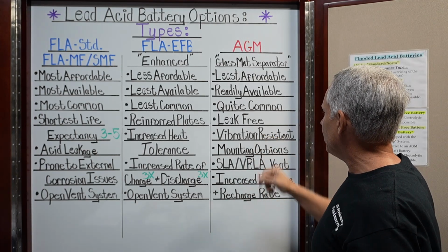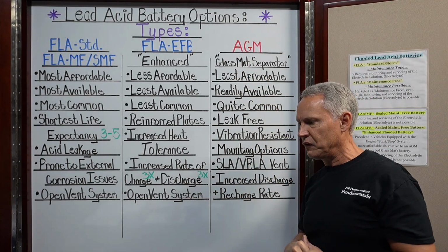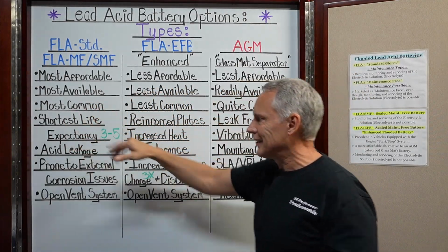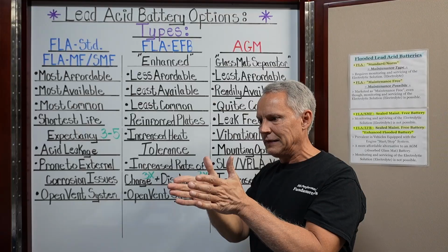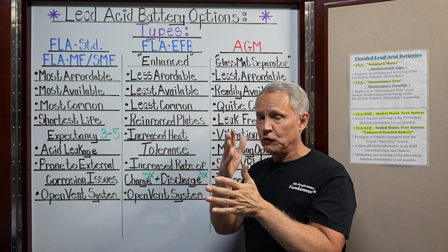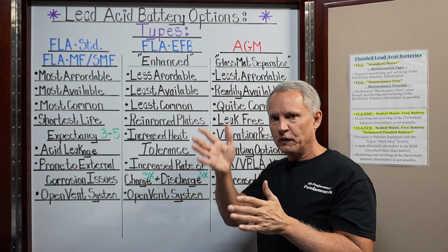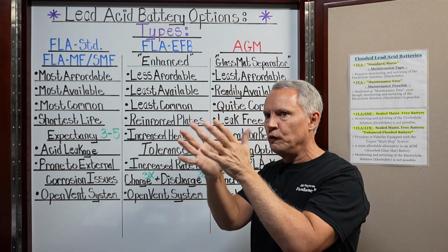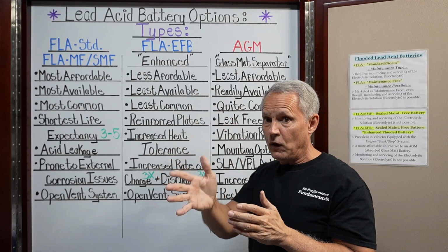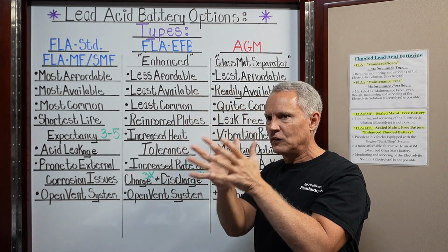They are very vibration resistant. The reason is the design of these batteries: there are two lead plates, positive and negative. Basically, the positive plate is lead dioxide, also known as lead peroxide. That's what the surface of the plate is. The negative plate is sponge lead, or spongy lead, right? So basically two soft metals. Lead's very soft, and the negative plate is also spongy lead, so it's porous, right? So they are a soft metal.